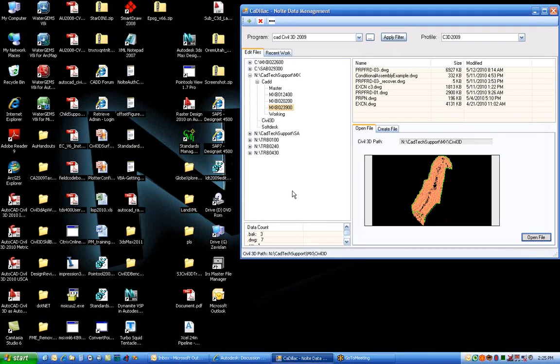But as I was building, hopefully you see how this scenario works: at different depths, we can say, okay, if it's less than 1.25 feet, just daylight directly at 5 to 1. If it's greater than 1.25 feet, then I want the 5 feet at 4 to 1, and then daylight at a much steeper rate.